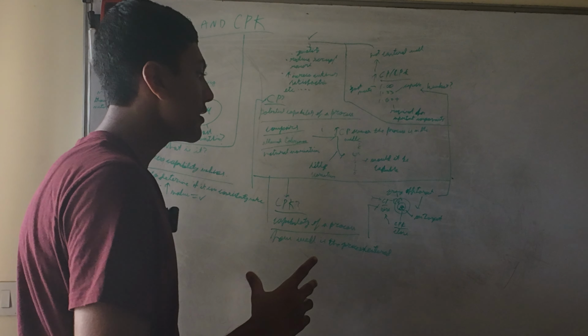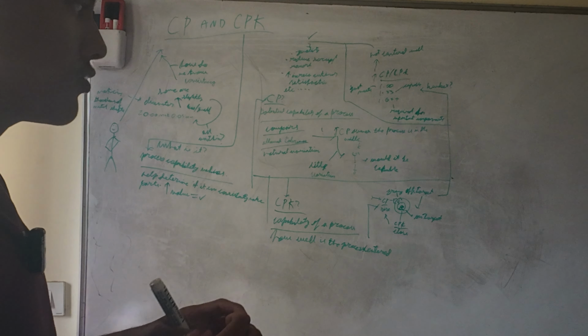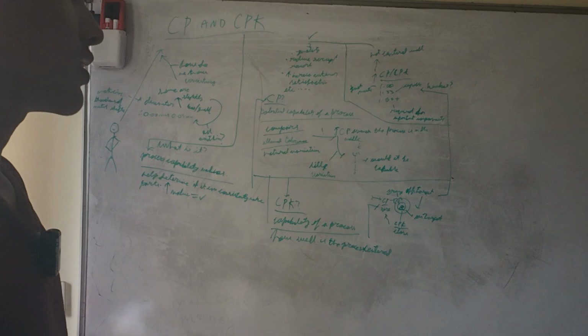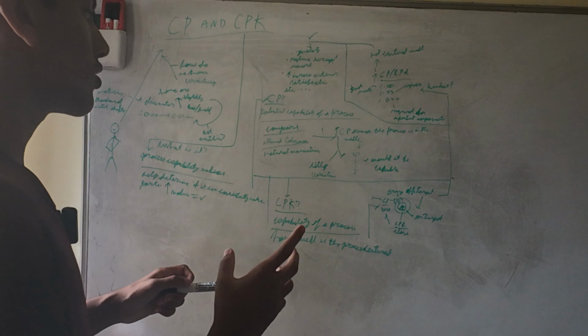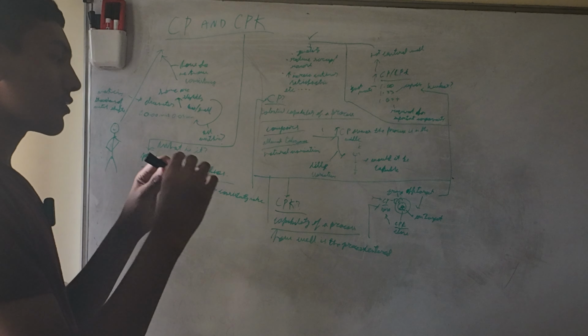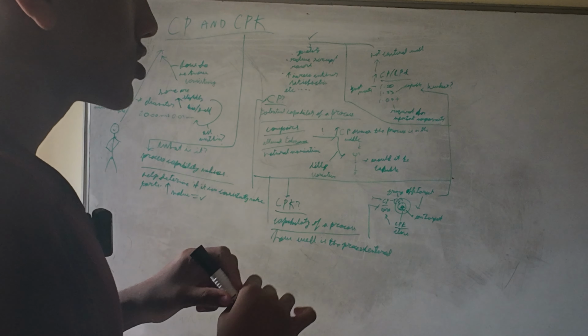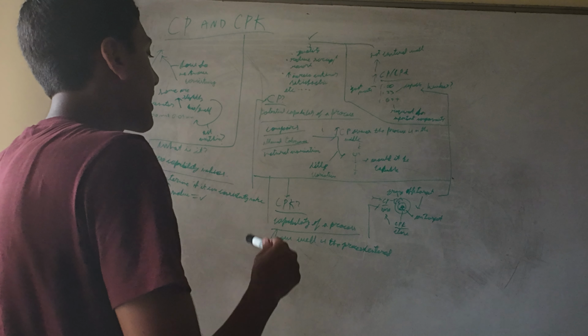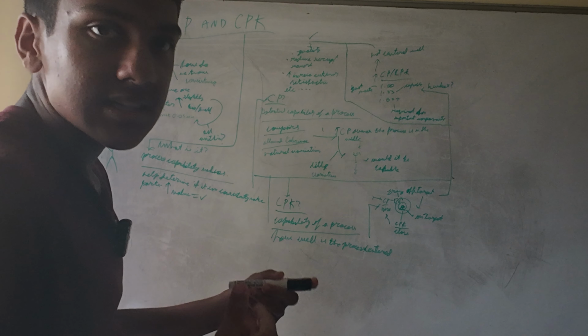While CP measures how many are in the group and how big the group is, CPK also does that, but also checks whether the darts are near the target and makes sure it's on target. So that's basically what CP and CPK mean.